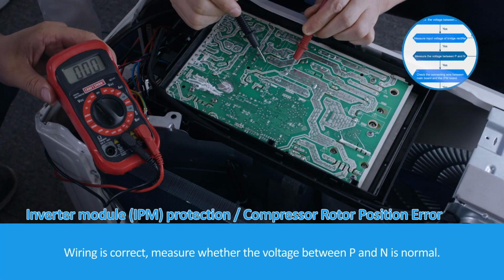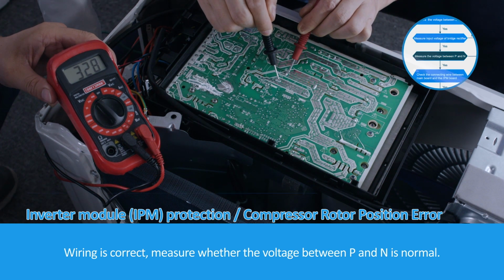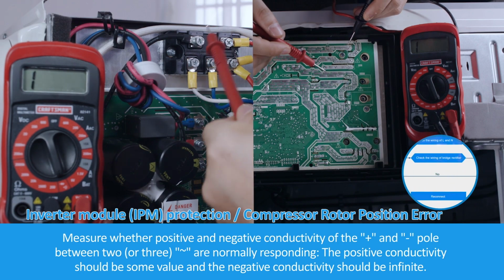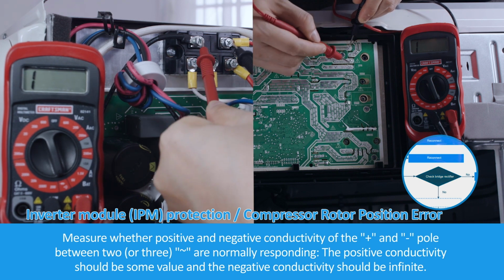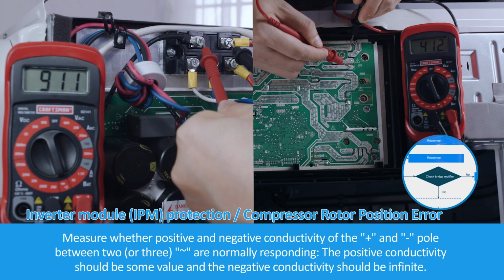Wiring is correct. Measure whether the voltage between P and N is normal. For the normal value, please refer to the table. Measure whether the positive and negative conductivity of the plus and minus poles between 2 or 3 AC are responding normally.